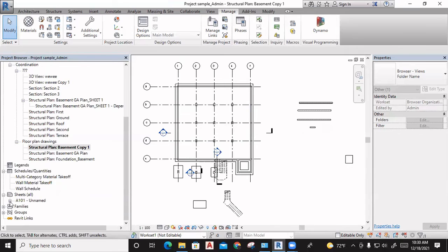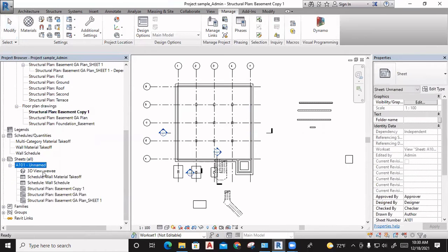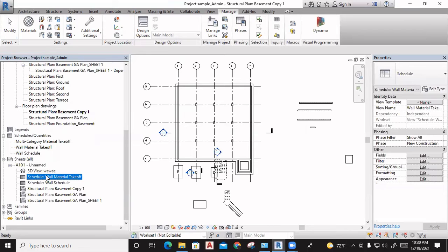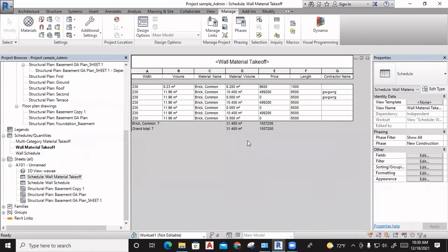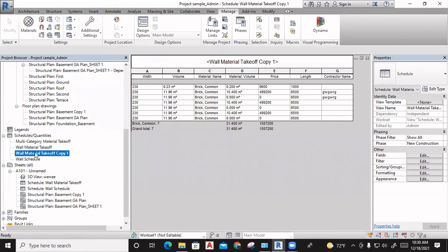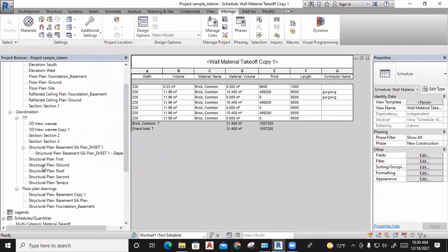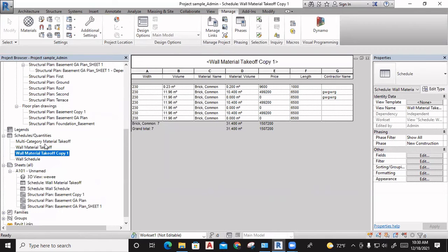And we have multiple ways to find a view in the sheet. Whenever a view is added, you have this view listed here. You can double click here also to go to the view. If you double click here, you can see it is highlighted now, and you are opening the view. But it is sometimes very difficult, for example, if you duplicate this view. Now it has some name, and I have to categorize, assign, and keep it in some topic. Then I should find a way.